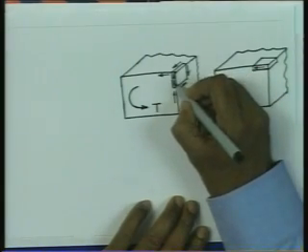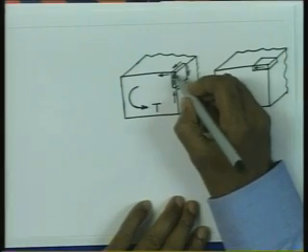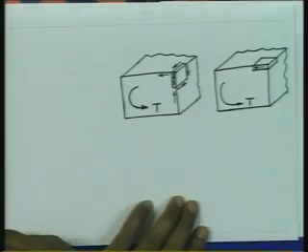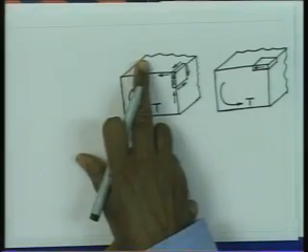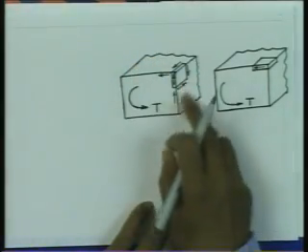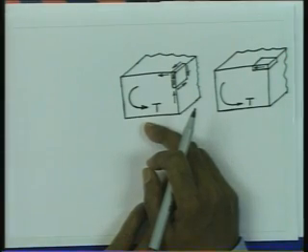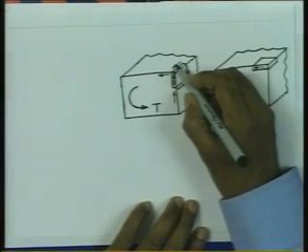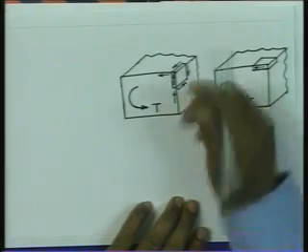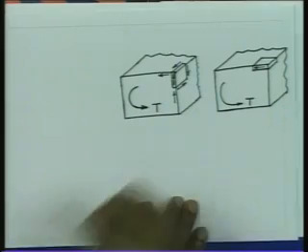So, if the stress is to be non-zero on this face close to this boundary, then this stress has got to be non-zero, but we know that these surfaces of the shaft are free of any external loading, therefore this is 0, and if this is 0, this is also 0, so also this is 0, this is 0. So, therefore, this stress is 0.